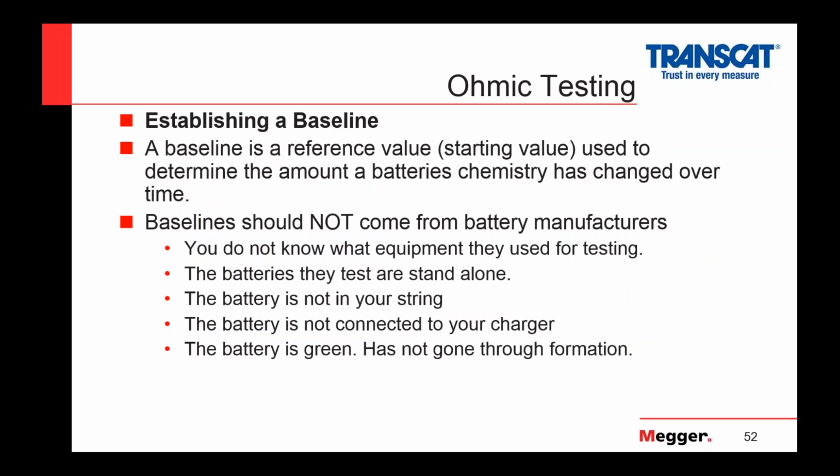And how do we establish a baseline? Sometimes I've heard people say this is like a magic number almost that you have to get from the battery manufacturer. No, it isn't. A baseline is a reference value. It's saying this is where I'm starting from, and this is my reference as the batteries age. Okay, and IEEE would tell you you don't want to get the baseline from the battery manufacturer because you don't know what instrument they used.